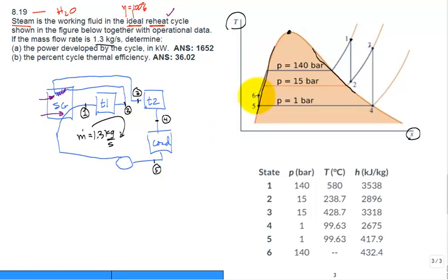You put it through the pump, puts it up in the compressed liquid state, state 6. And then you go from saturated liquid at that high pressure and you heat it. When it's heated in that steam generator, there's a phase where it's heating the compressed liquid to get it up to be at high enough temperature so that it starts to change phase or boil. And then there's a phase change from saturated liquid all the way to saturated vapor, and then it continues and is heated to be superheat, and that's up in the superheated steam region at state 1.